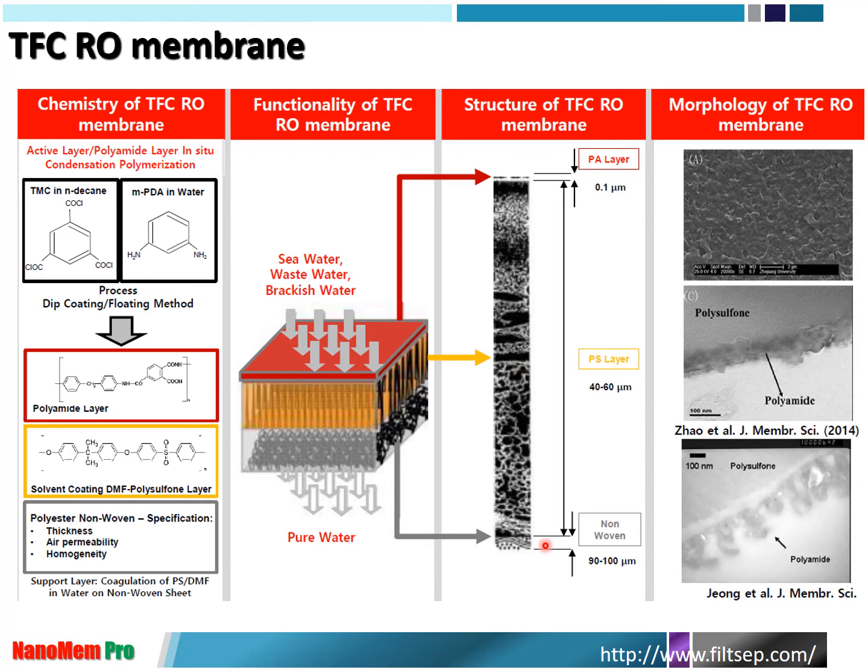So if you look in more detail at the polysulfone and polyamide layers, this is the polysulfone layer, this is the polyamide. So you can see some ridge-and-valley type of polyamide layer is produced when you utilize the polymerization of MPD and TMC. And then this can be nano size. A water molecule is around 0.3 to 0.4 nanometer, while sodium chloride is around 0.6 nanometer in size. So you have to separate sodium chloride and water, which means this polyamide, in terms of pore size, is about 0.5 or 0.6 nanometer, which will separate the water from sodium chloride.